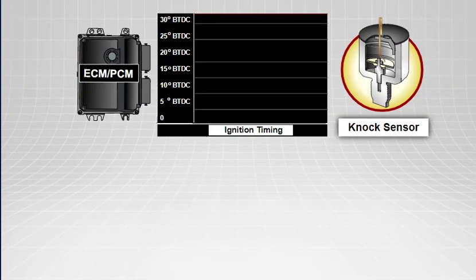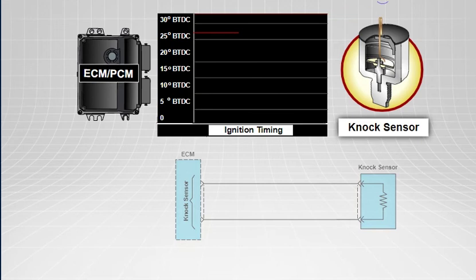The knock sensor is very similar to a microphone. It detects the vibrations caused by pre-ignition and outputs a voltage signal to the ECM. The ECM then adjusts ignition timing to eliminate the pre-ignition condition. Under normal operation, based on knock sensor input, the ECM will advance ignition timing until pre-ignition occurs and then retards timing slightly to maintain knock-free operation. A malfunction of the knock sensor circuit can cause pre-ignition and engine-damaging detonation because the PCM won't know to retard the ignition timing when pre-ignition is occurring.